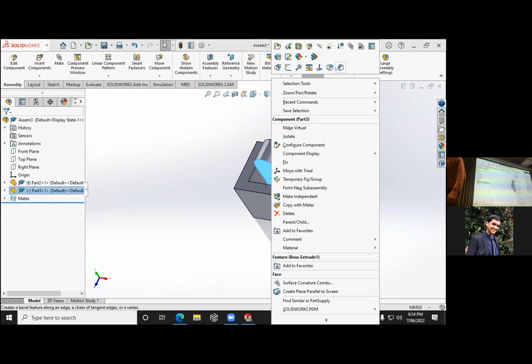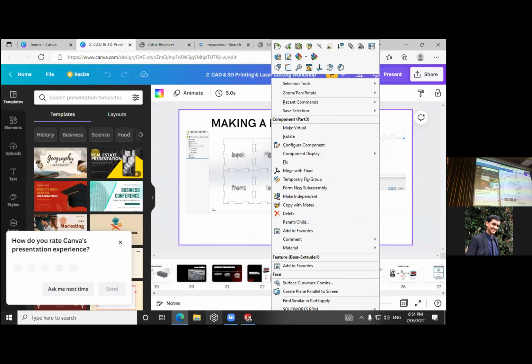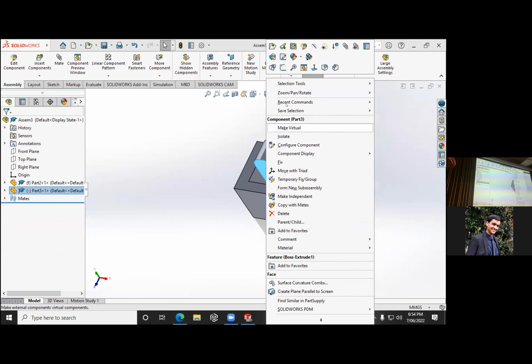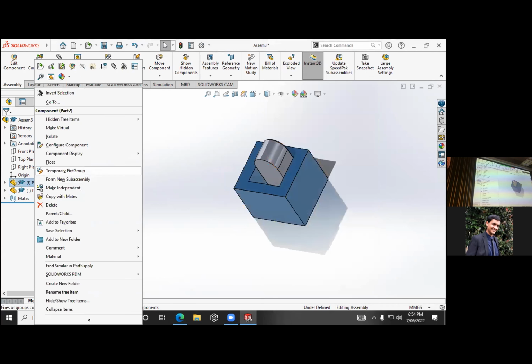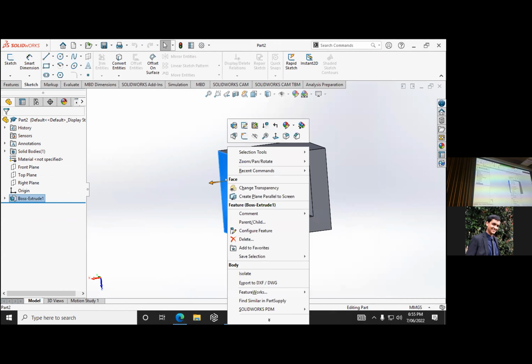Can I show you something? So in Fusion, you would go to the surface, press P to project the surface onto a sketch, and then save that sketch to 2D. The sketch will be 2D. Yeah, create a sketch on the surface, right? Press P to project the surface, and you can get a 2D projection. But you can't just pull it. Yeah, and then you also have to do it manually as well. I know that's an app. That's not a plugin that can convert different models where you have cross sections. The layers of the cross sections, right? Like a dinosaur, very small cross sections. Yeah, you can do that.